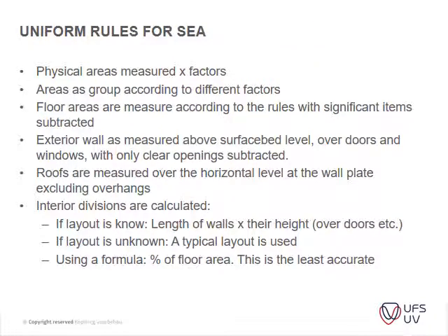Okay, the uniform rules for the storey enclosure area. So this is important, to know just the standard rules that apply to this method. Physical areas are measured and multiplied with your factors, as we've seen. Areas are grouped according to different factors. Floor areas are measured according to the rules, with significant items subtracted. Exterior walls are measured above surface level, over doors and windows, and only clear openings are subtracted.